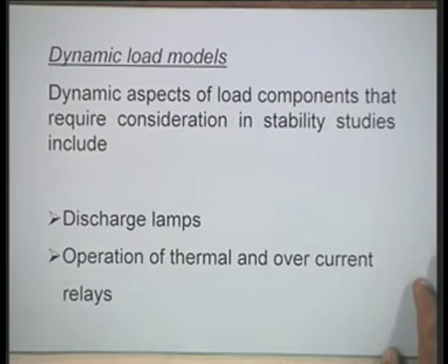But there are many loads which need to be modeled in a dynamic way, and particularly this dynamic load modeling is needed when we are doing inter-area oscillation studies. That is, we want to study the behavior of the system when it is subjected to inter-area oscillations, the long term phenomena. Similarly, when we are studying the long term or mid term stability or voltage stability of the system, dynamic load models are also required.